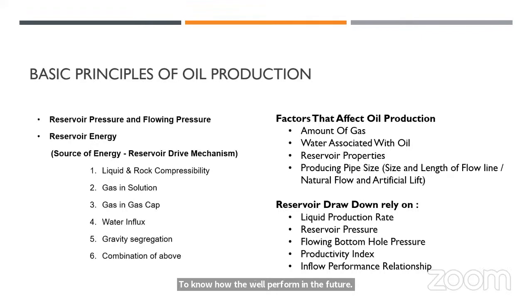In other cases, if we have a water drive mechanism, we might expect the influx of water. So we need to do some sensitivity analysis of water percent in our well model to know at which percent of water the well will cease to flow. So to understand this concept of reservoir energy, it is mandatory for us to plan for our sensitivity in the well model during the well modeling.